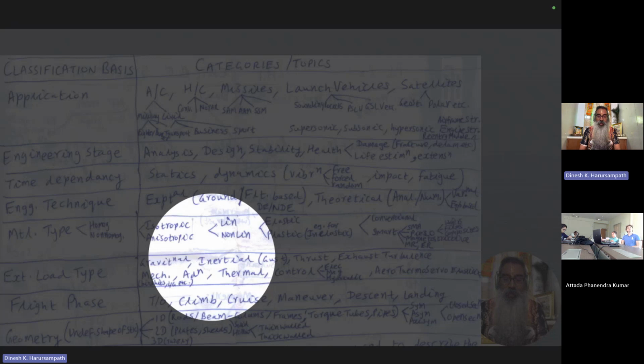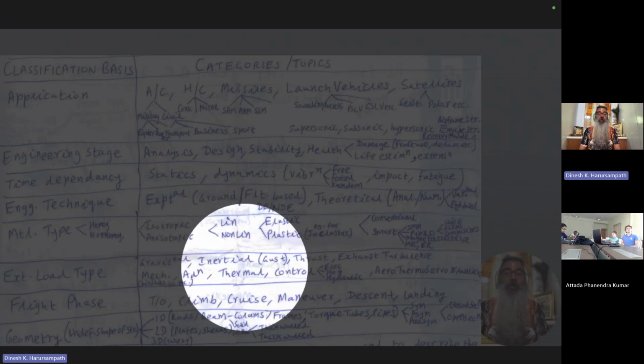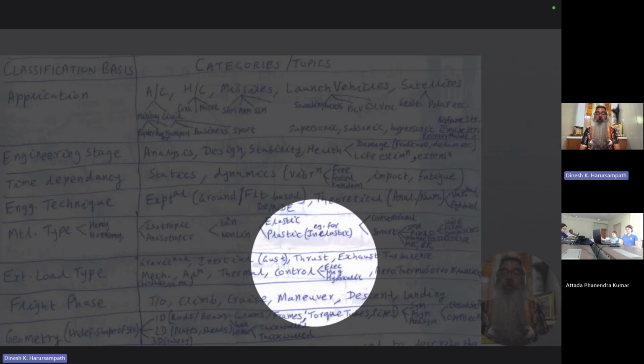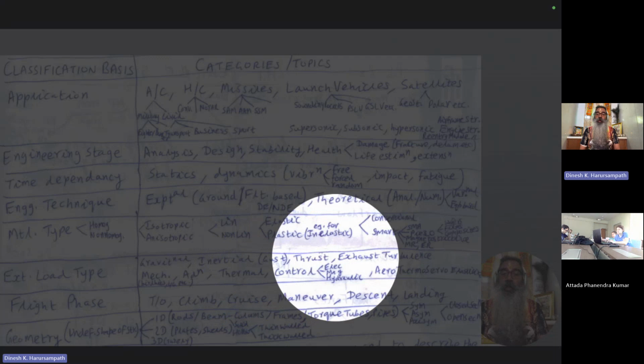Right. So the next thing is, of course, the thermal loads, which you already talked about, especially important in engines, but also in aircraft flying over various ranges of altitudes. Next is, of course, from the engine, you get the thrust, and that thrust load acting through the axis of the engine. And also some of these engines have vectoring nozzles. So you will have the nozzle, which is changing its axis through certain actuators, and therefore the force direction changes from the nozzle. And this is especially for fighter aircraft. You will see thrust vectoring taking place.